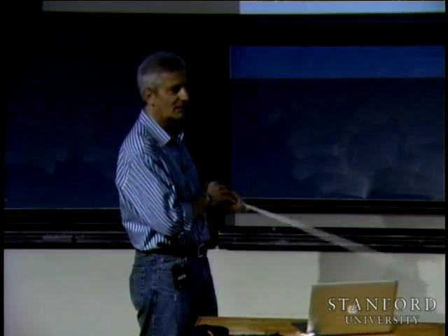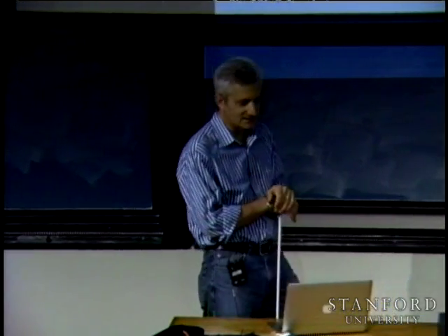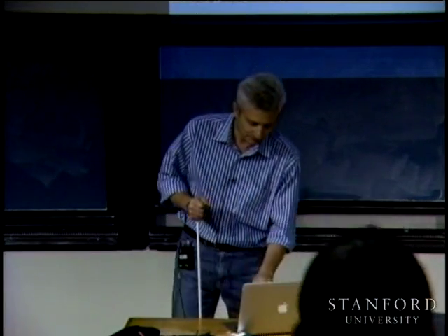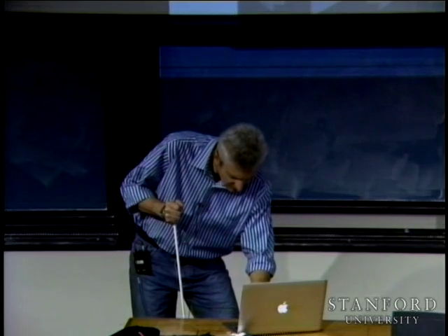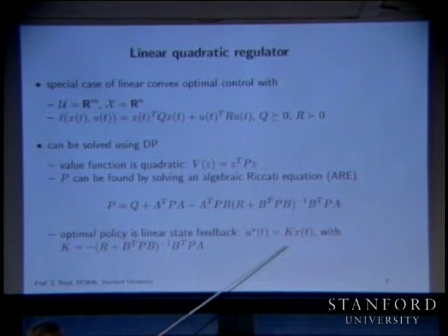Okay, so if you've seen this, you probably know this is extremely widely used, even in cases where systems aren't linear and so on, and it is unbelievably effective. State feedback gains like this just work really well. In particular, it's sort of like least squares. It's almost like magic, in the sense that when you synthesize state feedback gains like this, it's not interesting if the state is small and u is small, but if you've got 20 dimensions and five inputs, that's 100 numbers in there, and the 100 numbers just come out. It's just like calculating a pseudo-inverse and then doing image processing. It would have taken you a long time to adjust those 100 numbers by hand to get something that even works, let alone works so well. So this is widely used. Okay.